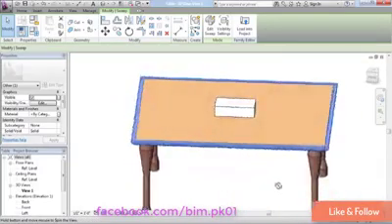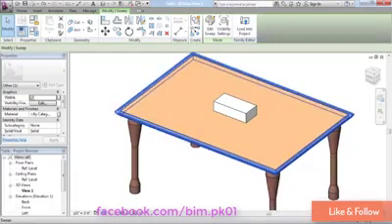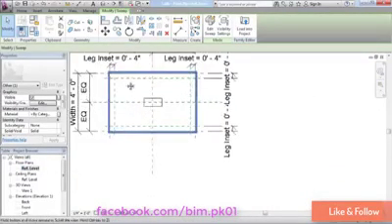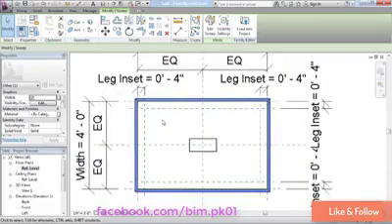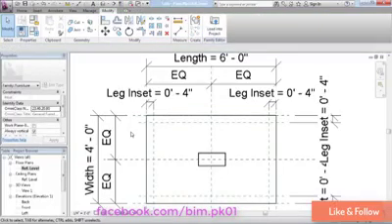and then you'll see the sweep added around the edge of the table. Now, the only disadvantage to doing it this way is, as you can see, this has actually increased the size of the table. If I return to my floor plan view, you can see that that will definitely have an impact on the way we set up our parameters. Notice the length is referenced back to this edge inside, and now the edge is 1.5 inches larger all the way around. So I'm actually going to delete this profile because we're going to reapproach this in a subtractive kind of way.